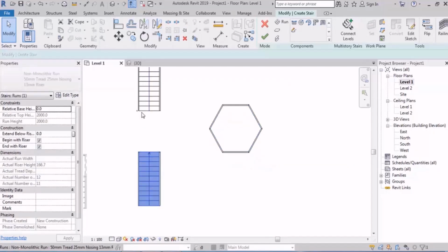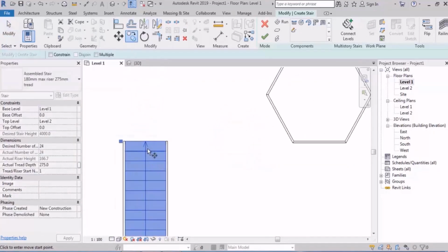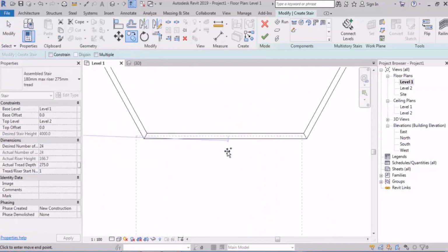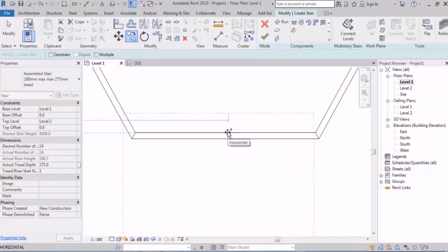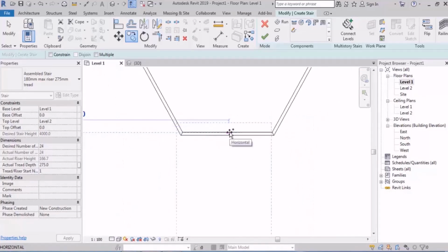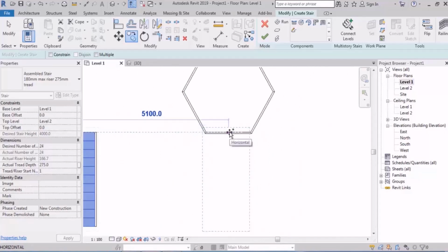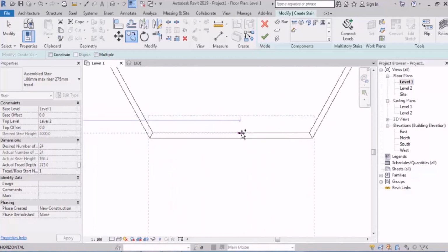So I select this and then copy it, and then I connect it from here. The first or the second line? That's right, the second line. Now, something funny happened here, and that's I can't put it on the first line. I can't even put it on the midpoint of the second line exactly, because this line is nearly in the direction of the other line. So other snaps are not working now.